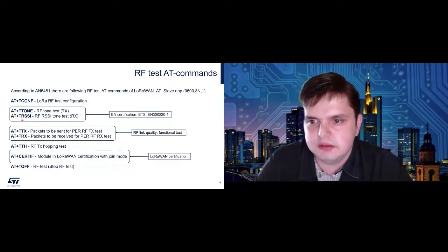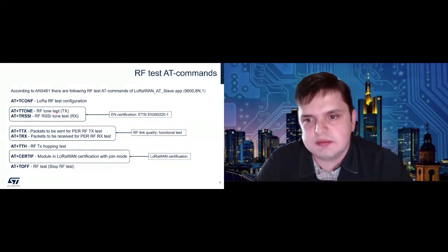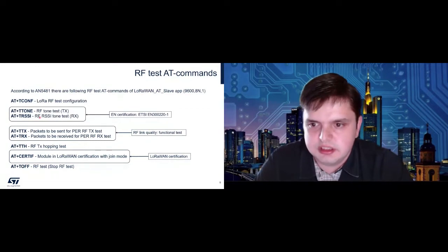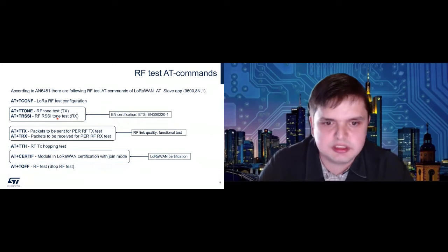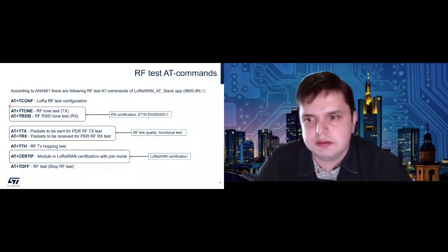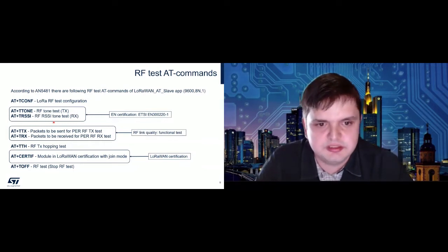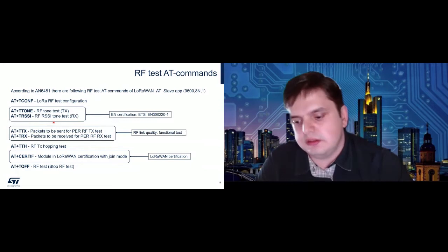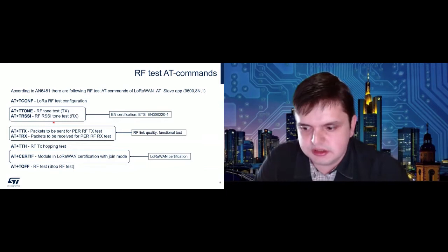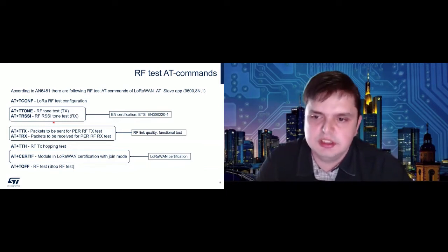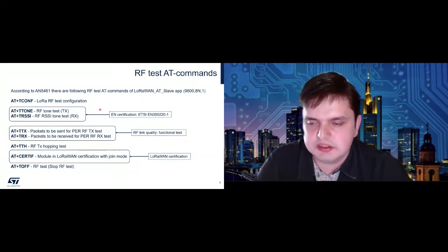So basically TTONE is a simple unmodulated wave transmitted on the board, and its counterpart is the RSSI tone test, meaning it listens to the wave and measures RSSI. These two commands are also important for the certification, or also during the development, you want to know how your RF matching performs on the PCB. So this is the test that is usually used in the RF lab.